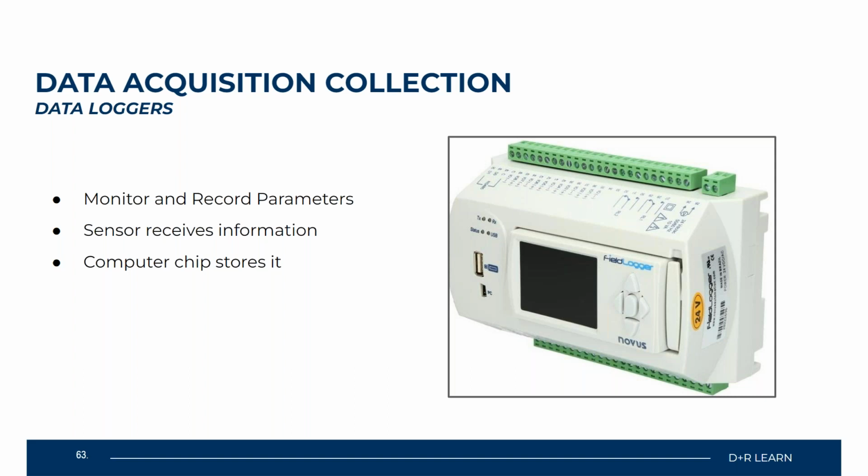And typically we're looking for a 10-degree delta T when we're taking those measurements. So that lets us know that the system is operating efficiently. Now, today, you don't have to do that. You can literally have one of these systems, your data loggers, embedded into your BAS system, and watch how much time you're going to cut from that human resource. You'll be able to utilize that human resource now in order to make any type of emergency repairs or repairs, period, that need to be done. Instead of going around and taking these measurements, your data logger can compile that information for you.